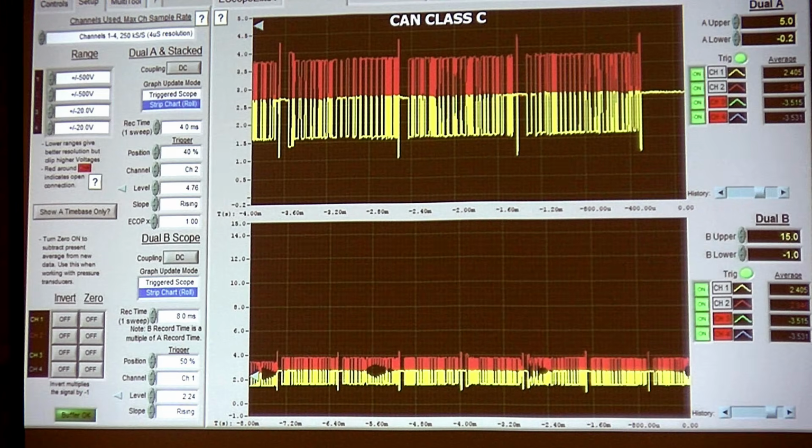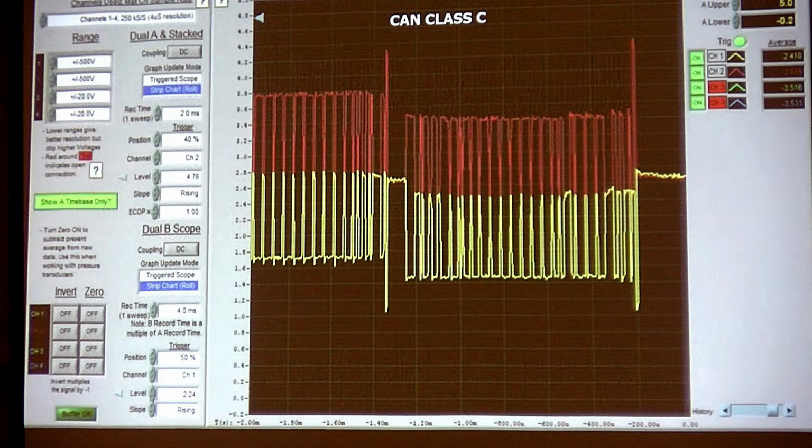It's because of the arbitration fields, I can't predict latency anymore. If you overdrive the bus, you no longer know when a message is going to get up, being an engineer. So that being said, I'm not going to do that. I'm going to add another bus. That's why BMW has 2 buses. And that has to do with the latency and the way that we arbitrate for the bus systems, the structure of the bus.